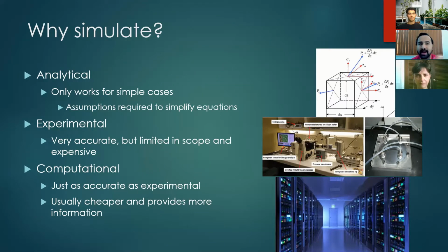So maybe you can analytically find a solution that says, oh, if you have a beam that is this long and you have a load that's this much on this end, and you assume this part stays the same, you can expect it to bend this amount and the stresses to be about this much. However, that requires a lot of assumptions. It requires you to assume that's a perfectly straight cylinder or a perfectly straight rod, or if you're trying to do something like Poiseuille for CFD, then you have to assume there's no height difference or no changes in geometry or anything. So this is really limited, but it's often a good place to start when you're doing your work.